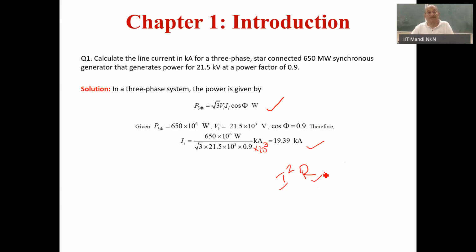Depending upon the maximum temperature withstood by the insulation provided to the winding, you have to restrict the temperature rise of the conductor, which is in contact with the insulation, the winding conductors. So what will you have to do? You have to provide a very strong cooling system in such a generator.